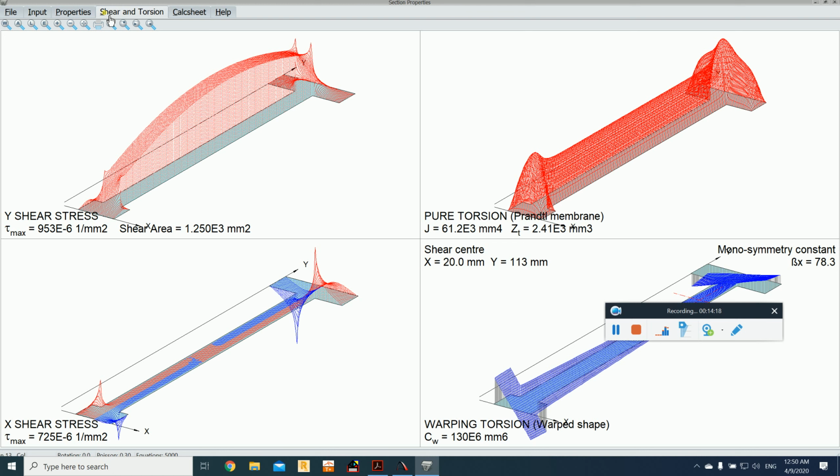As well, it will show you the shear stresses, the torsion, shear stresses of X, shear stresses of Y, the torsions where it will be located, and you can see mainly the stresses will be maximum on the joints wherever there is a difference in terms of the area, or there is irregular joints, like the connection between here and this particular portion.